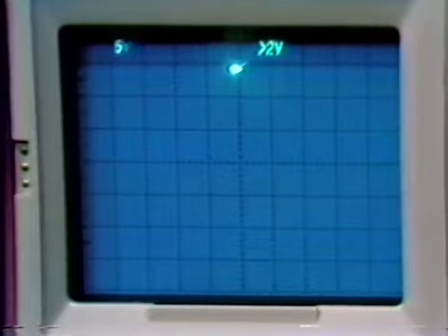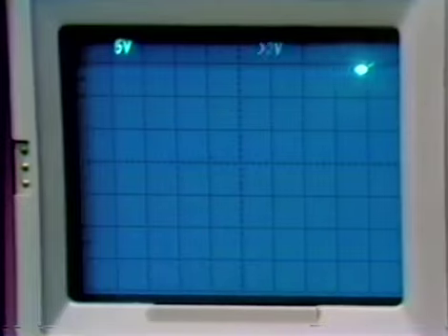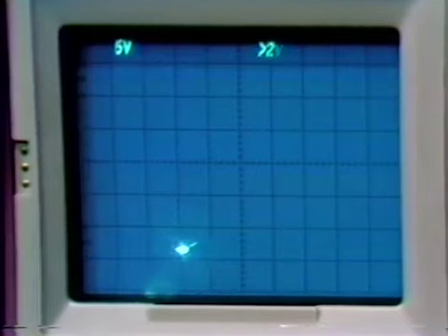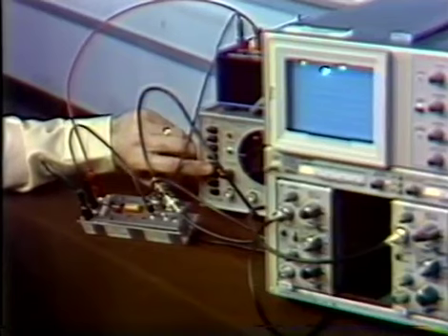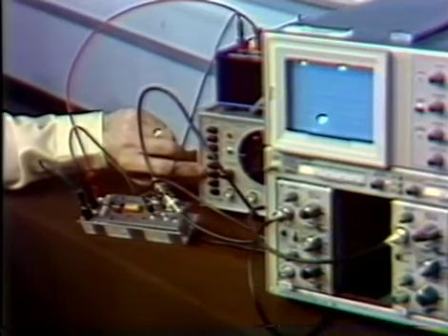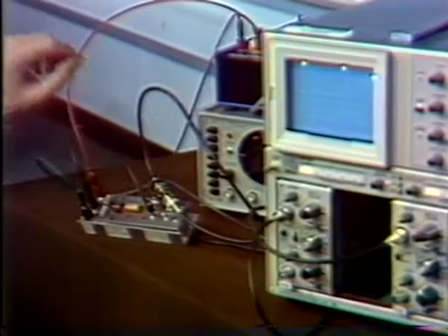The positive going input, now it's going negative, switches once again, passes the original transition point before it switches to the positive state. So that's simply the characteristics from the Schmitt trigger. And as I say, that's mechanized using a commercially available integrated circuit comparator.